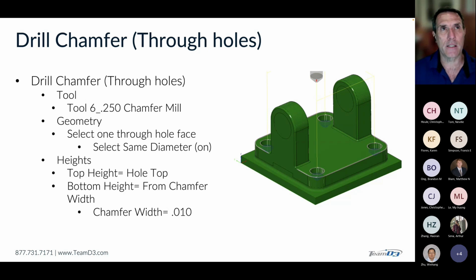In the advanced machining extension, it can look for features such as drilling operations, and based on the size of the hole, because as mentioned before, you can put in clearance holes. So a clearance hole for a certain size bolt is going to be a certain number drill. It can automatically select things like that. Drills are the easiest thing to do because they come in specific sizes for specific purposes. I'm not aware of the ability to do that with mills and things like that.